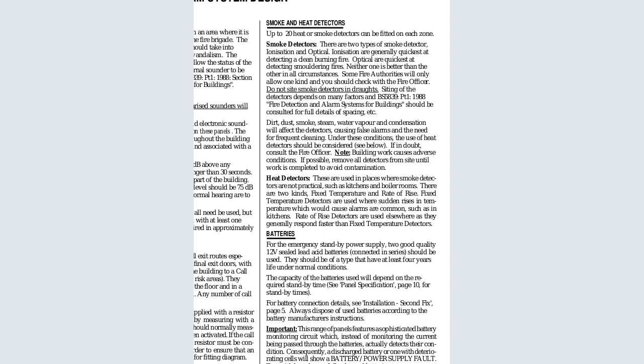So do not site smoke detectors in draughts. Siting of detectors depends on many factors, according to the BS standard, that is BS 5839. And if you want to know the IEE regulations on the fire alarm detectors, or even the call points, callers and sounders, you can get it in the BS standard, that is BS 5839. You will be asked this in your exams, which state the BS standard or the IEE regulation for fire alarm. So you should be able to know which one will give you that detection.